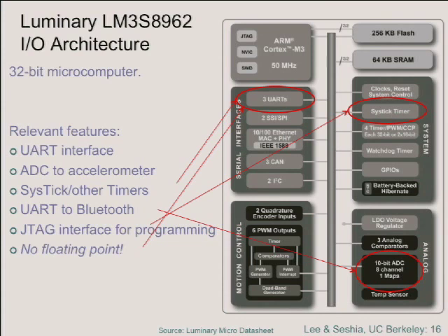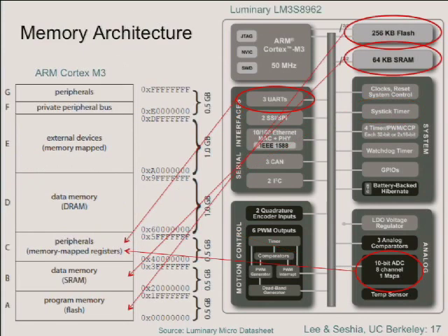The question is about using multiple lines. We had UART and we always did other stuff while waiting for UART to send or receive the package. So if we have multiple lines, we don't have to send packages over all the lines, but we can actually send information a lot faster. So we send one package on the first UART, and then we can send the next package on the second UART. Yeah, that's in the case of UART.